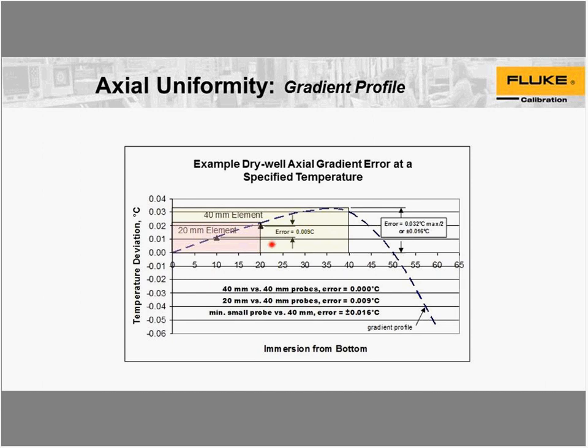Now, in a lot of cases, if you were just comparing all the same size, you wouldn't really have to worry about this entire thing. What you have to worry about is the variation in the construction of that thermometer. Can that element move up and down a quarter of an inch or something inside that device? You might have to work with some manufacturers to determine that. They're clearly never quite at the bottom. They have to leave some clearance at the bottom, and that can vary somewhat depending on how it goes together.